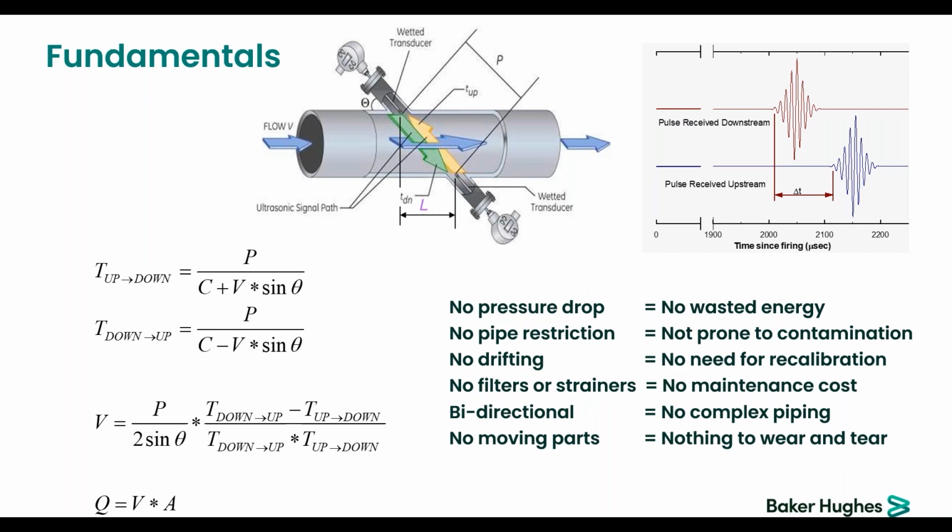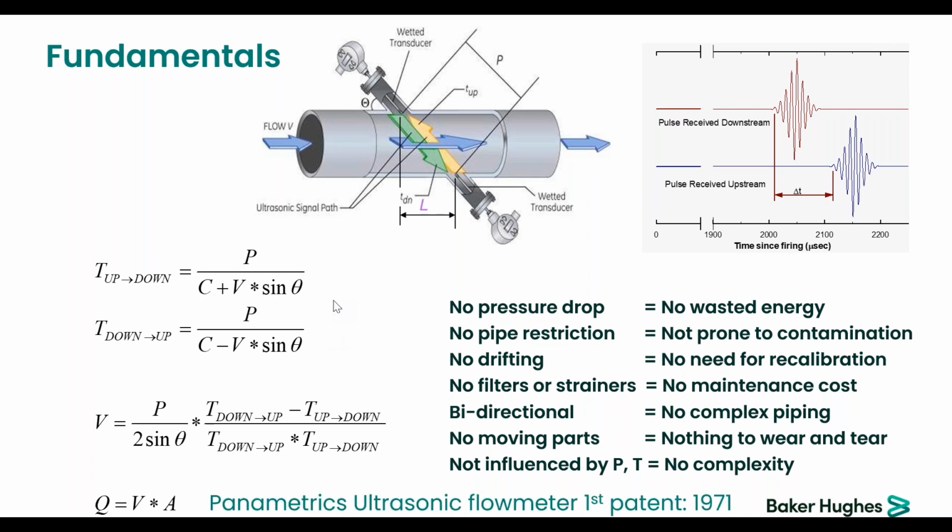There's no moving part inside that will be prone to wear and tear. So it's something that will last for long. And it is not influenced by the pressure and the temperature. So it's not very complex as a system. And I put that one because on the equation of the velocity, you have P and T, but that's the path length and the time. It's not the pressure and the temperature. So with this,